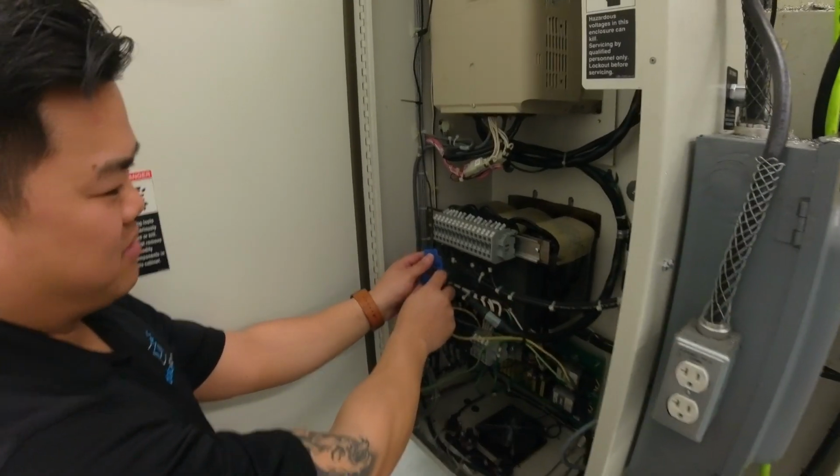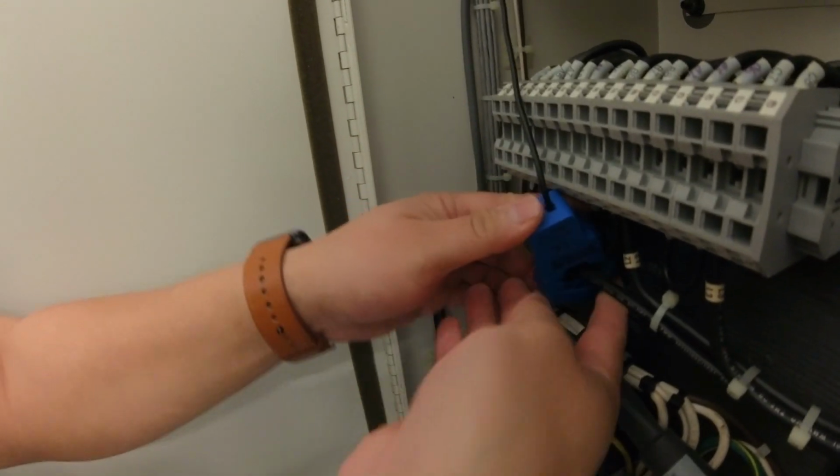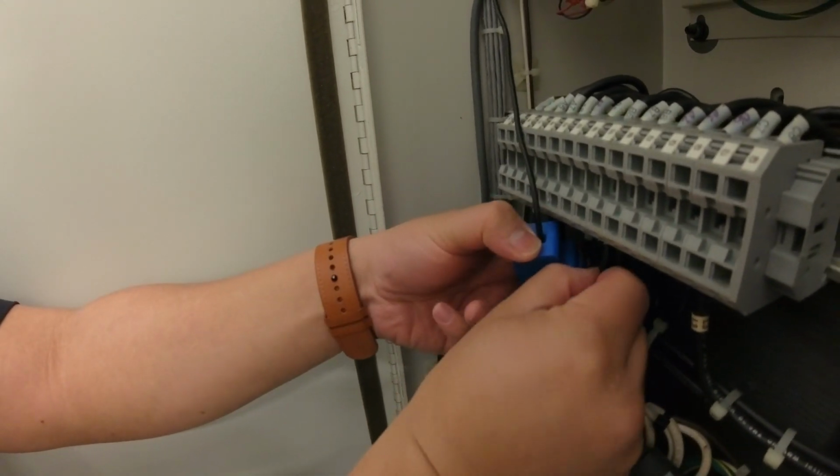In our Connecticut case study involving the adoption of digital machine monitoring technology, the manufacturer selected sensors that did not directly interface with the production equipment controls. The sensors that were installed monitor equipment status by using an amperage sensor clamped around a machine's power cable and measuring the electrical current flow through the wire.